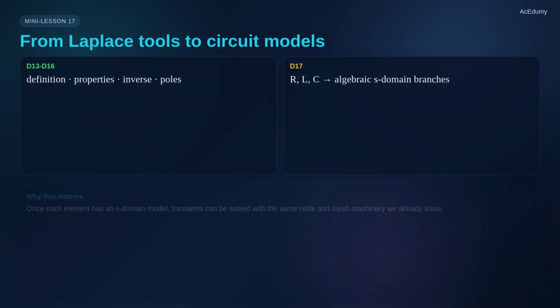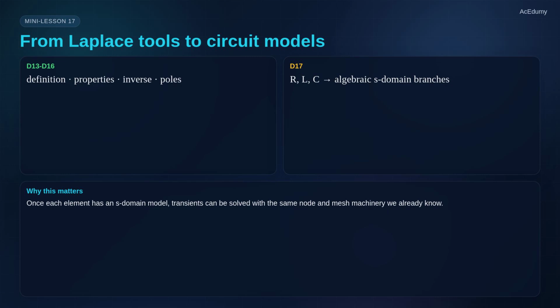We have built the Laplace toolkits: definition, shifting rules, inverse Laplace, poles, zeros, and endpoint checks. Now we connect that toolkit back to real circuits. The goal is simple. Take each time domain element and replace it with an algebraic model in the S domain.